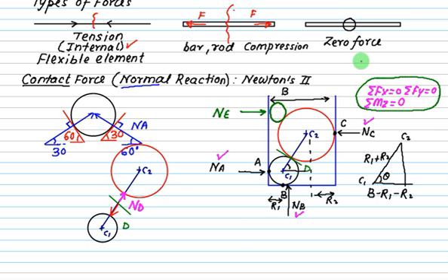So basically FBD is introduced. You can draw different FBDs and you can increase the number of equations. But remember, each set of equations is the same: sigma Fx 0, sigma Fy 0, and moment 0. But you can repeatedly use these equations for different figures. So this is the idea about the free body diagram. And that's why the free body diagram is always used in mechanics.